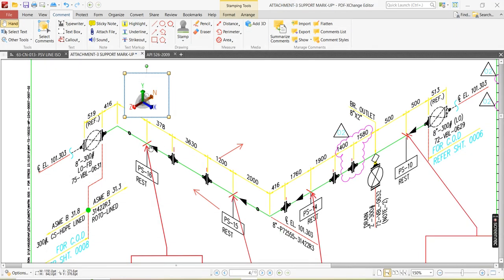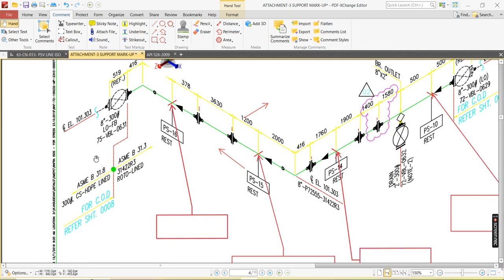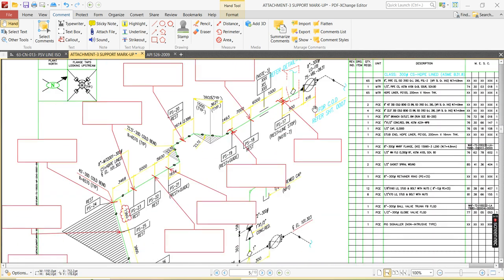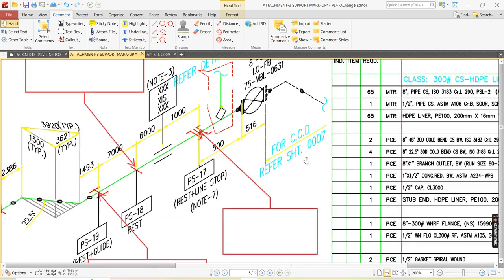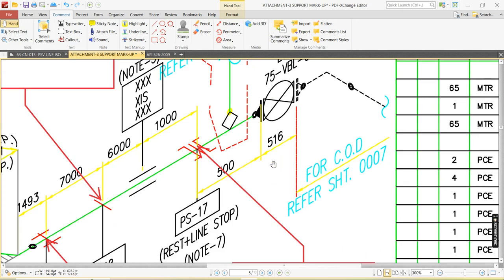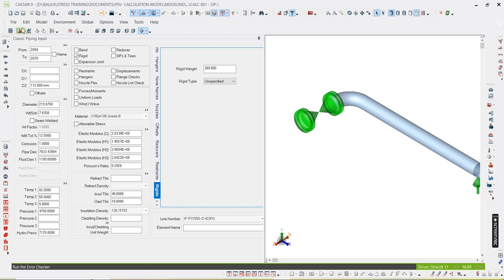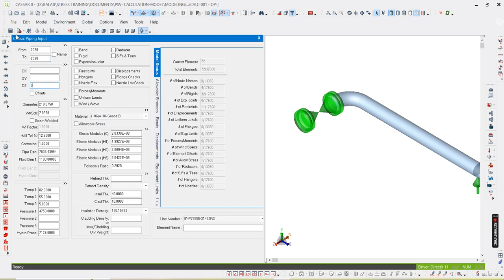Okay. So again, the line is getting continued to the next sheet. It is continuing in sheet 8. So it is from sheet 7 it is coming. So we have modeled up to the flange. After that, after the flange, one support is there, that is at the dimension of 500. Okay, go to the next node. At 500, you enter the support.